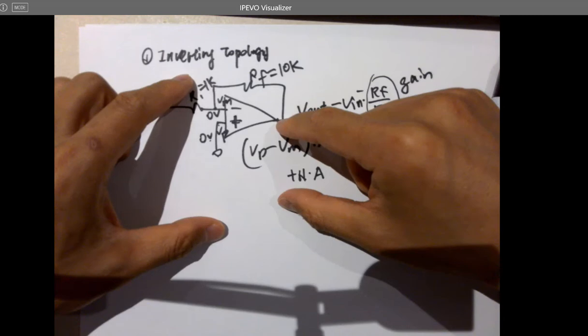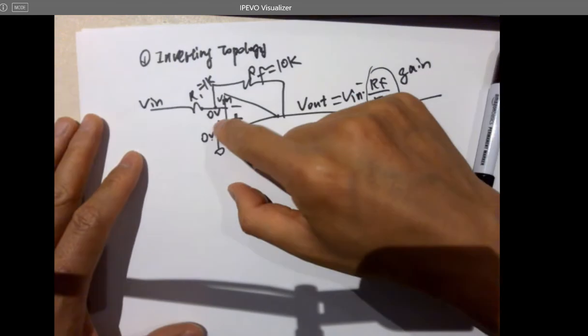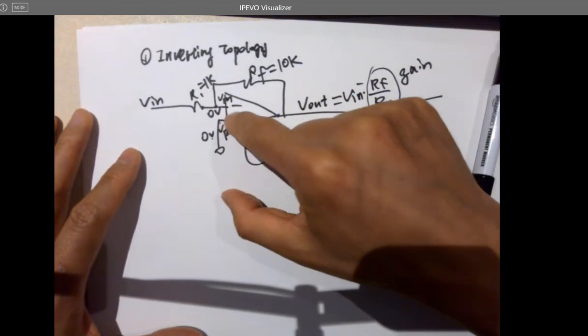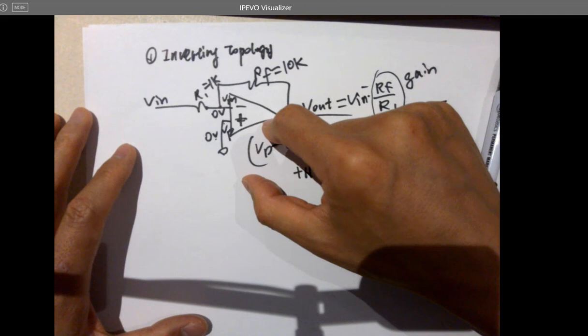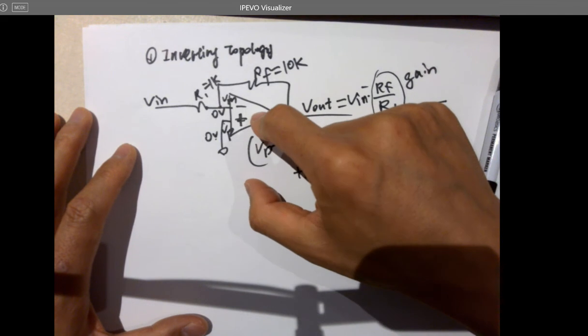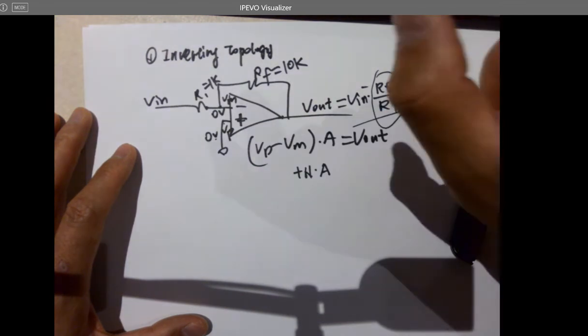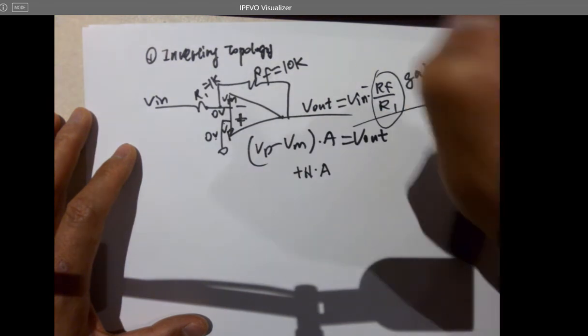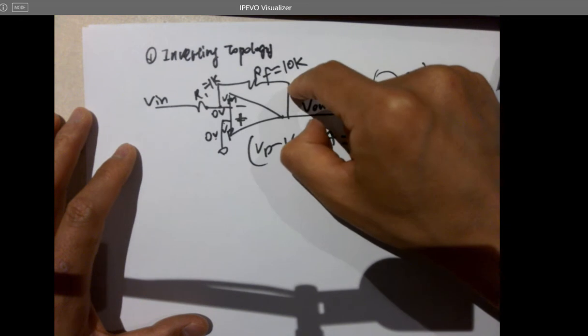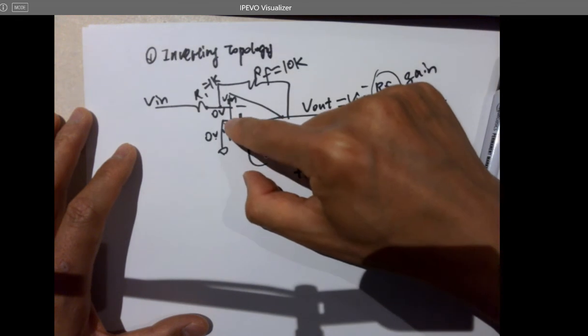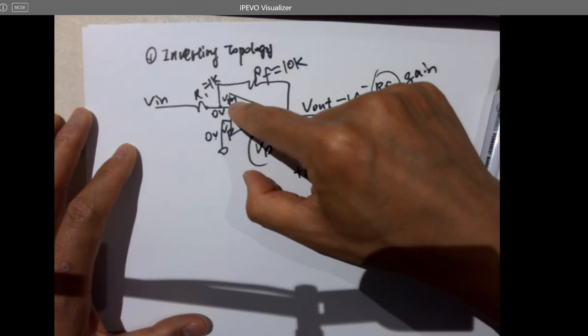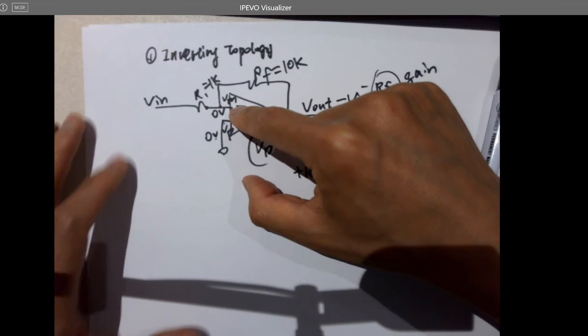That's how I understand it. So these two terminals, as long as the legit OpAmp is not failing, it's going to have a huge open loop gain. Open loop gain, keep in mind. That open loop gain plus that negative feedback is going to force these two terminals to be very close voltage values. You can consider this as the same voltages.